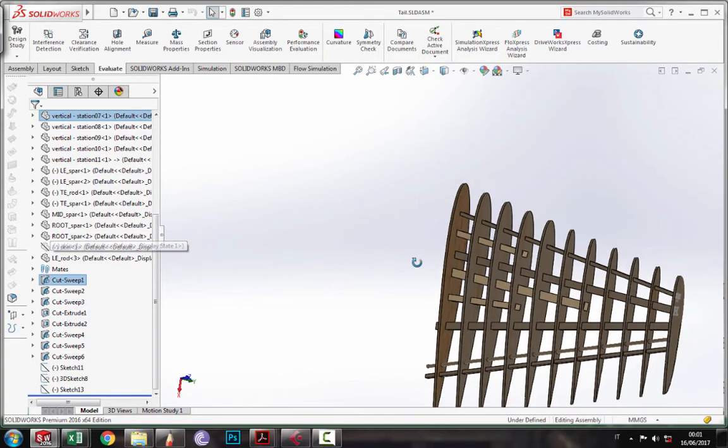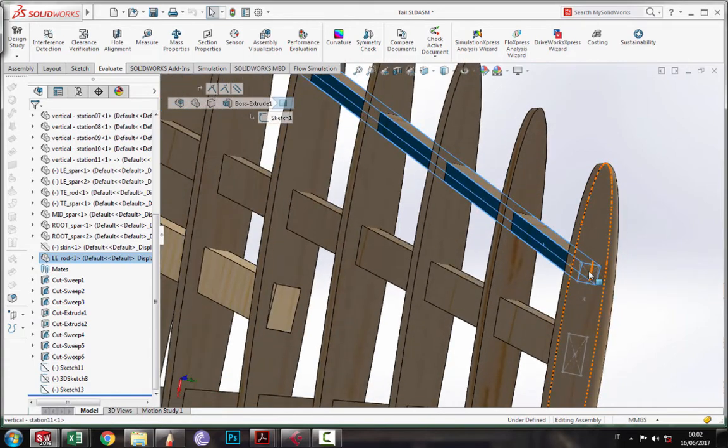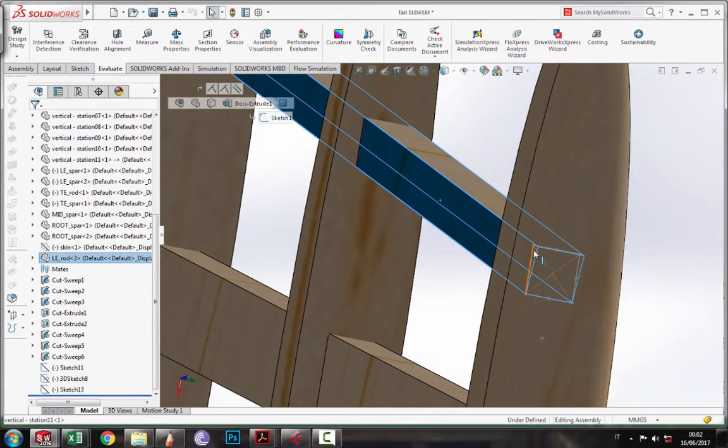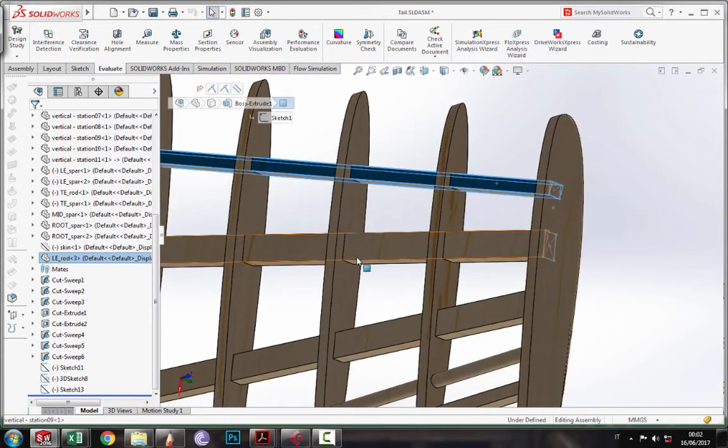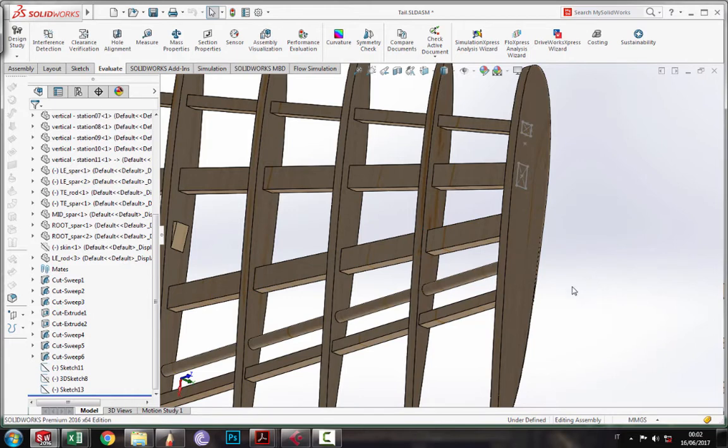Also, when you are positioning the spars, this rod, sorry. Okay, first rule: make the geometry with right angles in order to avoid rotating of the section like this. If you choose a cylindrical rod, the wing can rotate on one axis. If you use vertical right angles, it cannot rotate.